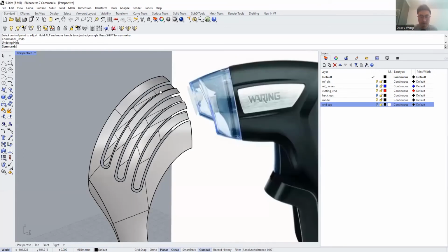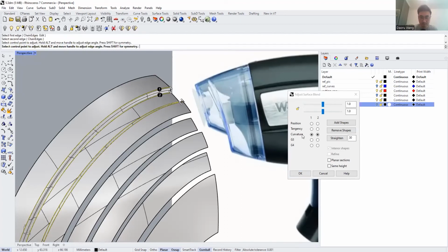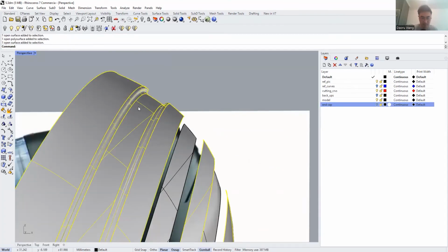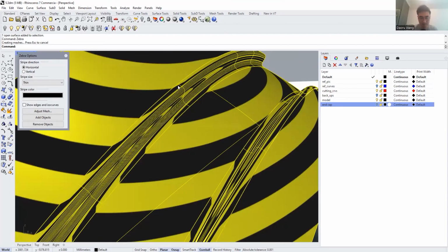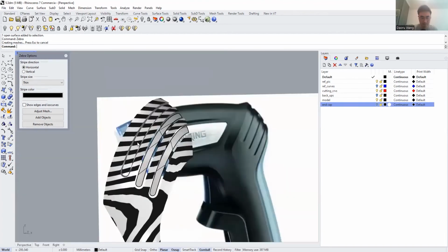Okay, so since now we have isolated everything, let's start to blend the surface together, which we have done many times. First edge, second edge, I will choose G3. Let's be picky, hit OK. And you can see that the continuity, no doubt, has been preserved in a great shape. You can see that all the edge conditions are great, right? Yeah.